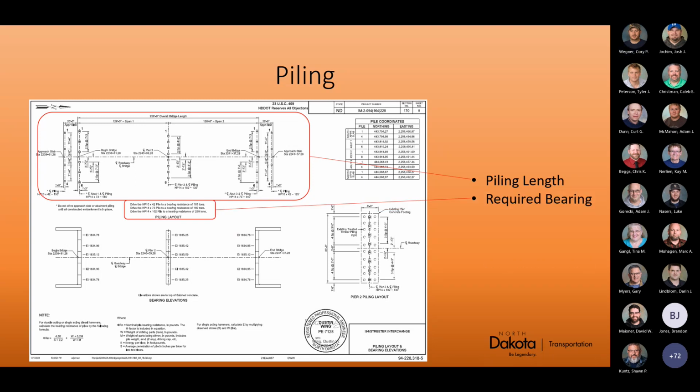Required bearing. You see that here. You'll need that to make sure you hit that bearing, because the designers have calculated the load that that pile needs to carry to support that bridge.